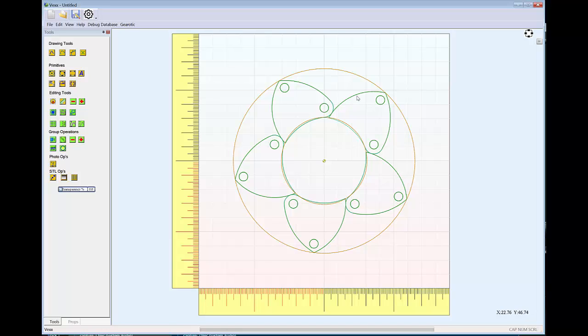If we just take for granted that it's a constant amount of power taken to open or close the vanes, that power requirement is going to be divided into how many degrees it takes to open them. I use about 40 degrees or so, but the shape of your slot is going to depend on exactly how much you have to turn that ring. So we need a way to measure that rotation.